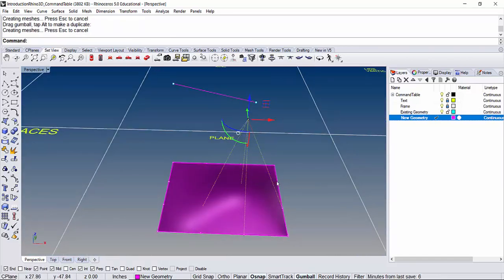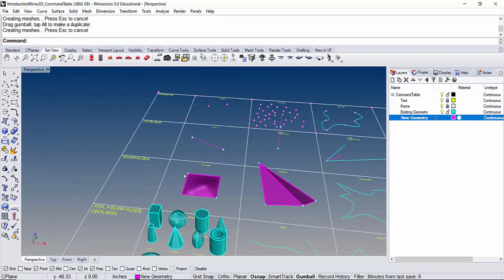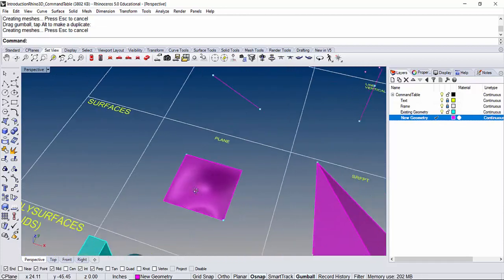So this is very similar to the way that when we have a line or when we have a polyline, there's only so much movement that you can have. But when you turn your curve to a 3-degree curve, or when you have more control points, there's more relationships that you can manipulate that way. So similar to our curves, our surfaces could also be rebuilt.